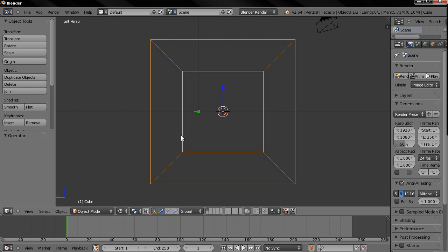For each point P in the 3D scene, a PO line is drawn passing by O and P. The intersection point S between the PO line and the plane is the perspective projection of that point. By projecting all points P of the scene, you get a perspective view.